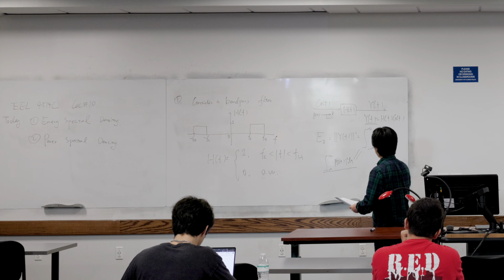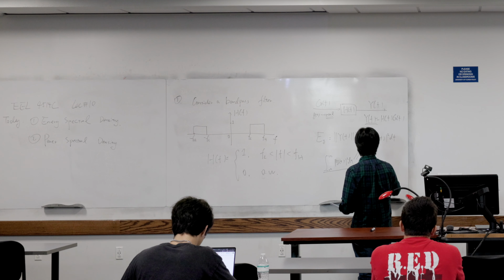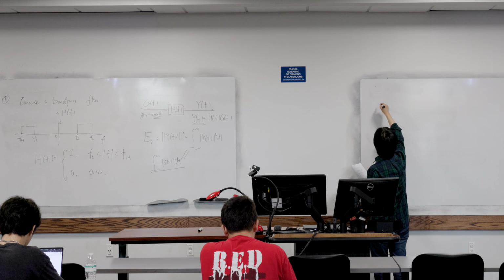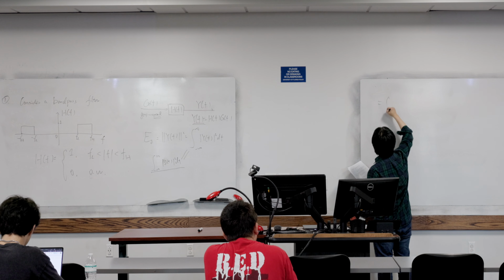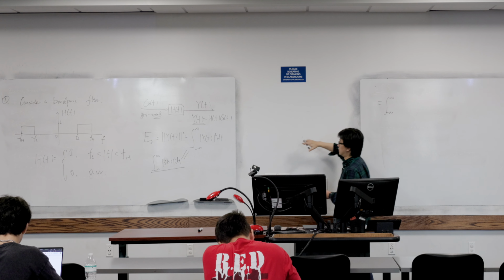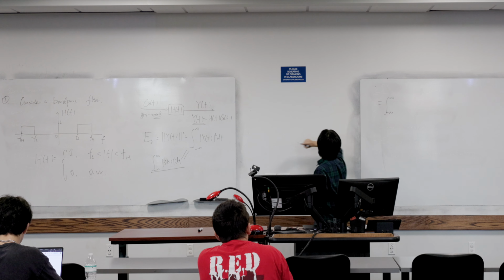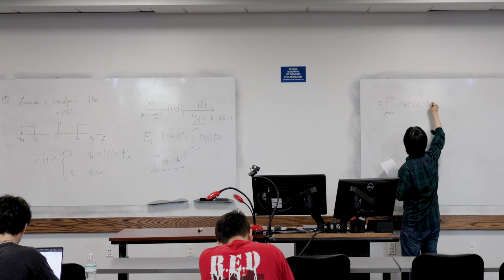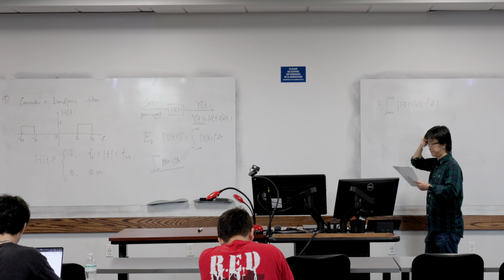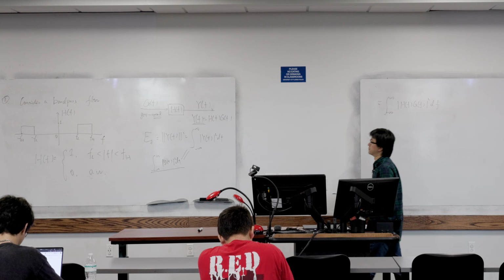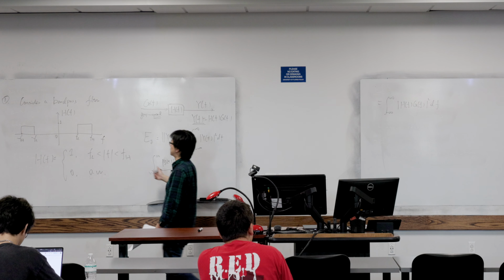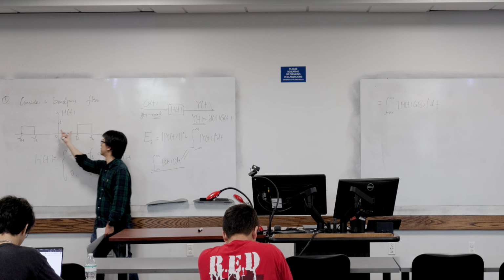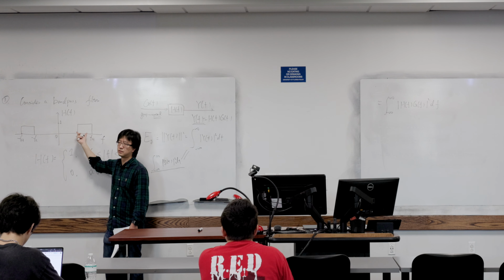With that said, we can do one more step. That equals nothing but we just plug Y(f) in here. Y(f) equals this, so that is |H(f)G(f)|² df. Now what is interesting is that because of H, only this part and this part are left, everything else will be gone.